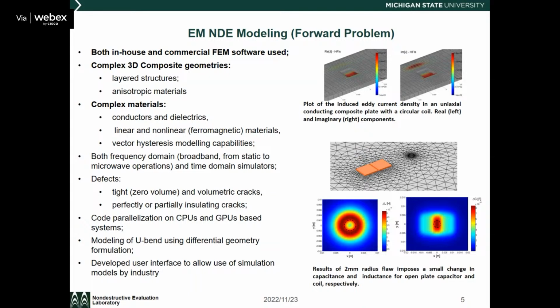Well, this is a very good question. Let me try to answer your question in two ways. When you have your composite fabricated, first of all, you have to understand what type of composite it is. Let's take a simple composite structure. Let's say I have a 0, 90, 0 degrees composite layup. In that case, the only difference between layers is a different orientation of the carbon fibers. And if you look at every 0-degree layer, you can treat them to be the same layer when you do the simulation.